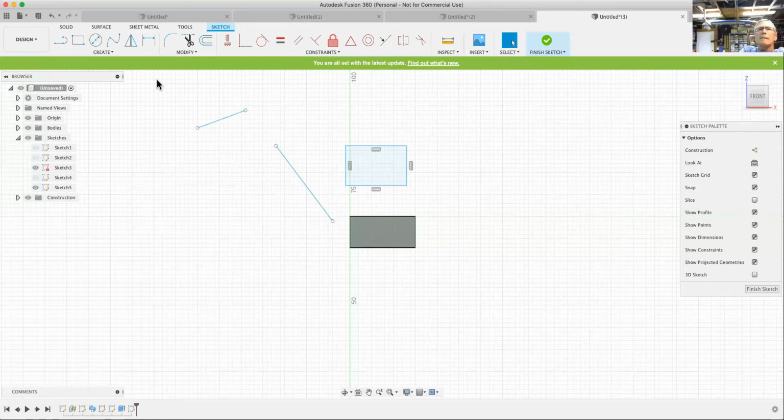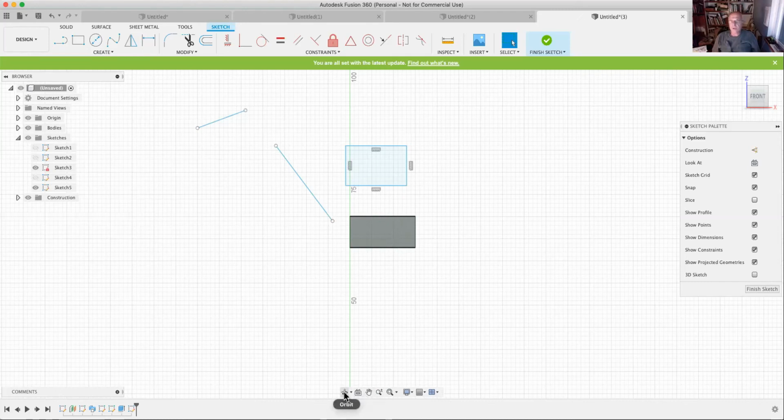Can I ask you a quick question about shortcuts? This has been on my mind for some time. To get to the panning tool or the rotate tool, are there keyboard shortcuts for those? Well, orbit, that's what I meant. Yeah, orbit is what they call it, and everybody calls it something different. If you hit the shift key and use the middle mouse, you get orbit.